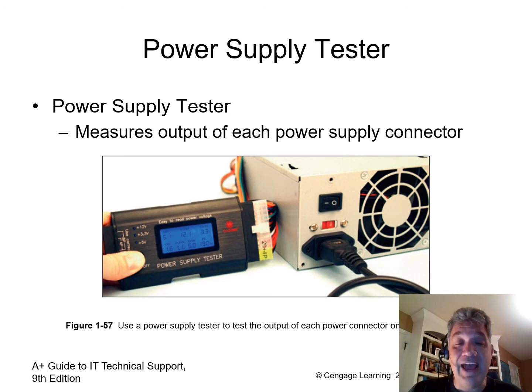But at the end of the day, if you suspect that you have a power supply problem, perhaps the fan has stopped working, perhaps you smell a burning smell, perhaps your optical drive stops running, etc., then these are cheap enough that it's probably a good idea, again, if you're not going to replace the whole PC, that you just go ahead and replace the whole power supply.